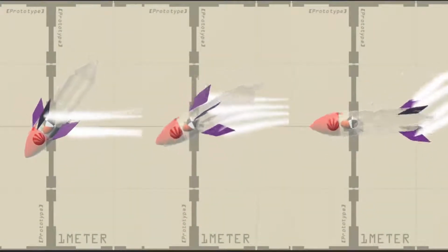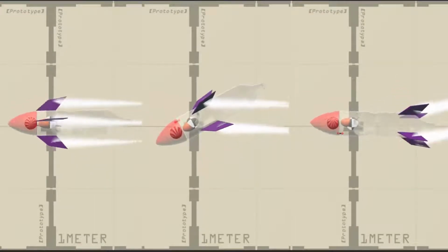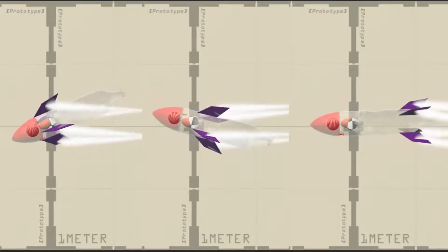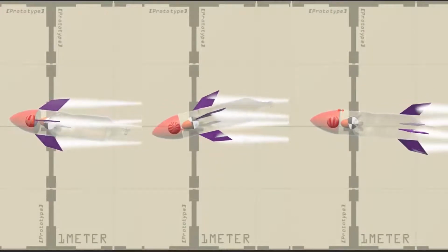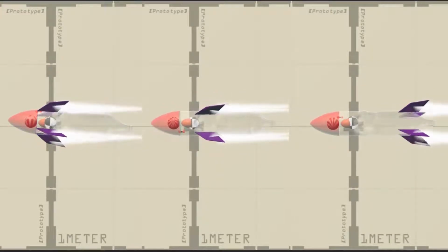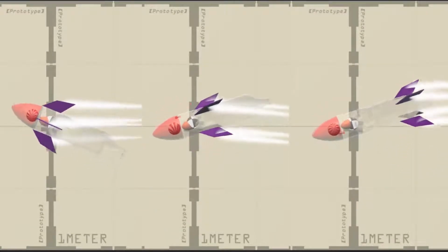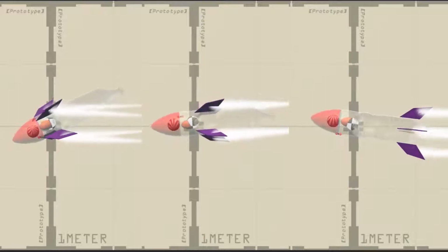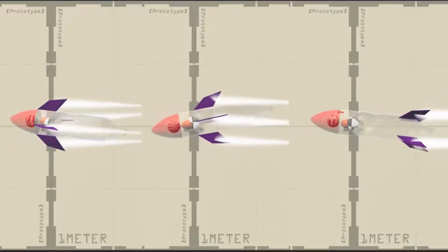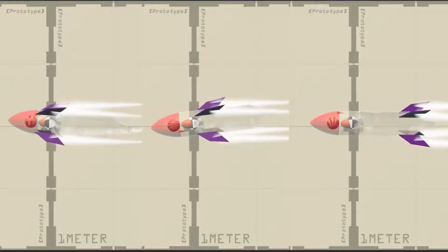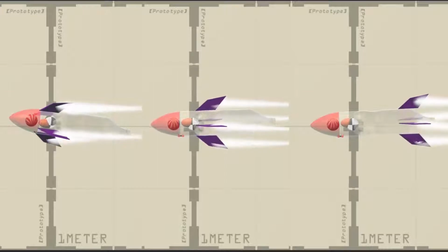Stability. The stability of the rocket is its ability to continue flying without being disturbed. The rocket is more stable when the center of gravity is ahead of the center of pressure. Therefore, having the fins closer to the nozzle moves the center of pressure closer to the nozzle, which allows the rocket to be more stable. It also reduces the risk of the rocket changing direction mid-flight. Having the fins further away from the nozzle and closer to the nose increases the instability of the rocket because the center of pressure may move ahead of the center of gravity.